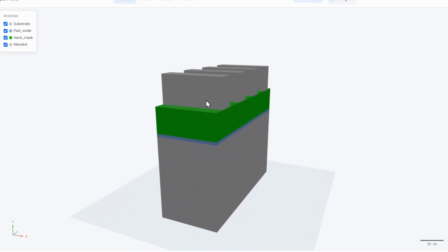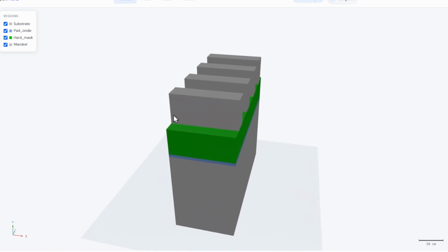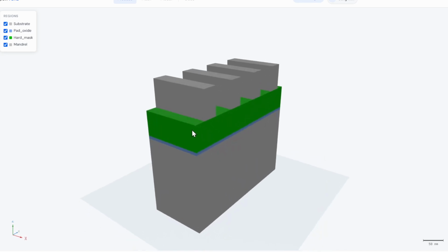And this etching process ends on reaching this silicon nitride, because we assume that between silicon and silicon nitride there is such a huge difference in selectivity that if we etch silicon, then we can only etch silicon. We cannot etch this silicon nitride.